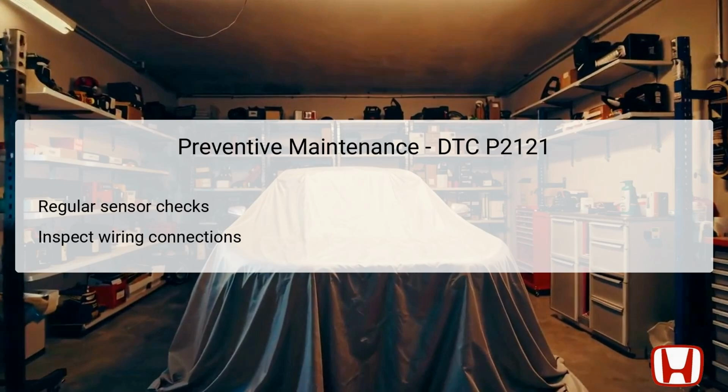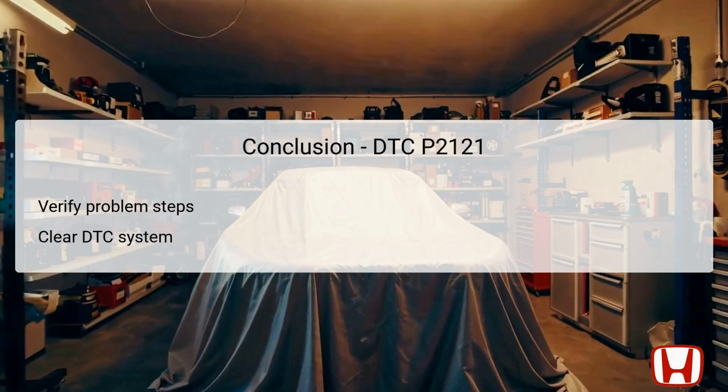In summary, diagnosing and addressing DTC P2121 involves a systematic approach that focuses on verifying the APP sensor's functionality and connections. It begins with using the HDS to monitor signals and progresses through carefully outlined steps to check the sensor itself and related wiring.